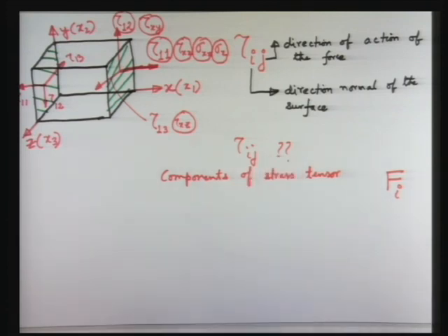So in that way, there are more classical and mathematical definitions of a tensor that I could provide, but it is not of importance to the audience that we are generally addressing at this level. It is important for us to just let the students recognize that it is a force per unit area, but the beauty of representation of this force is that it also depends on the orientation of the area. So it requires two indices for its specification. To that extent, I think it is good enough to represent the stress. Now there are issues,